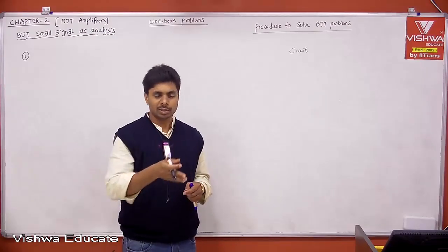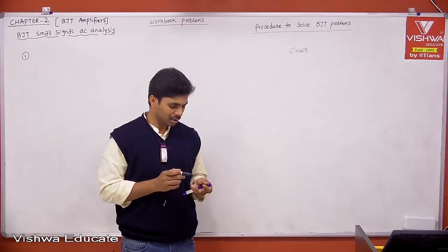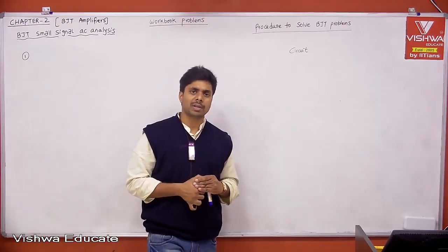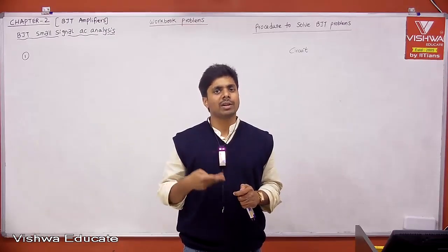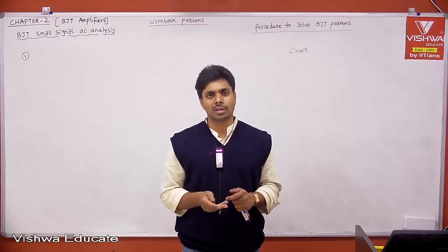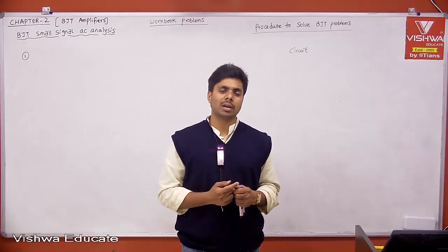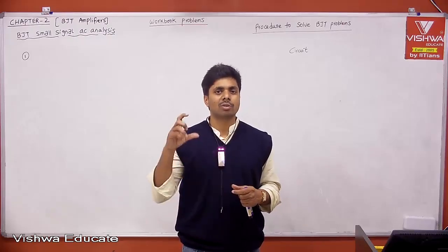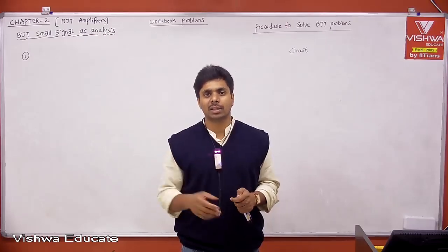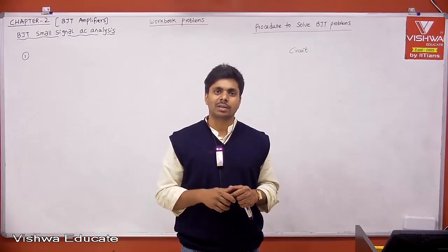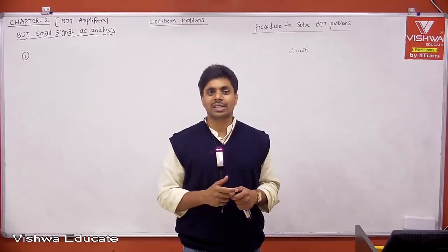Let us say we take this problem number 1, asking for voltage gain. Is it an AC parameter or a DC parameter? Definitely an AC parameter, because voltage gain, current gain, input impedance, output impedance, wherever we deal with AC signals, that is AC analysis. If I ask what the operating point is, what the output DC collector current is, what the output DC voltage is, what the power consumption by the transistor is, what the Q point stability or stability factor is, or finding the value of a resistor, these are all related to DC analysis.